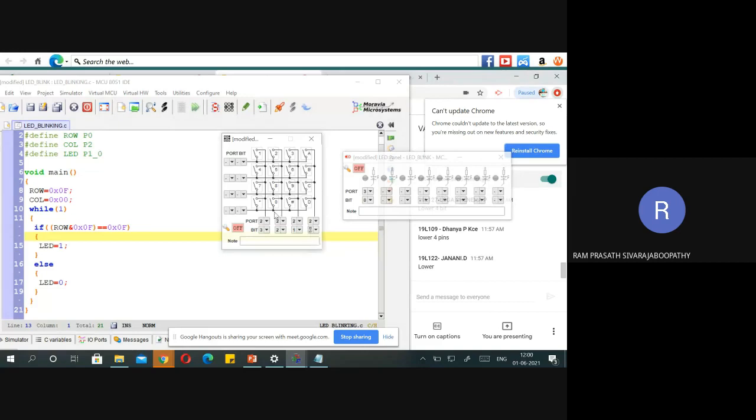Okay, similarly I have to use it here for port 0, port 0 with 3210. Only if we take these successive pins can we write the program easily using this kind of logic. You can use alternate pins, but the program complexity becomes much higher. Most matrix arrangement keys work in this fashion only. Even your PC keyboard works in this fashion only. Okay, so the hardware connection is done.